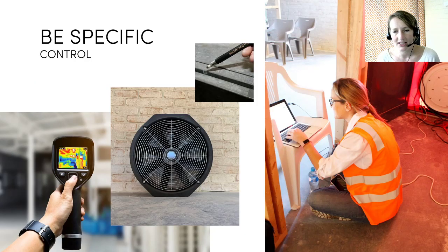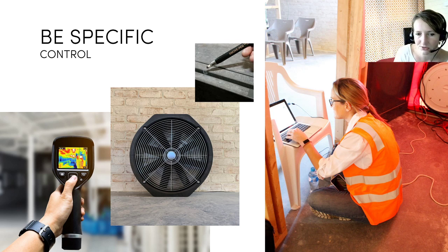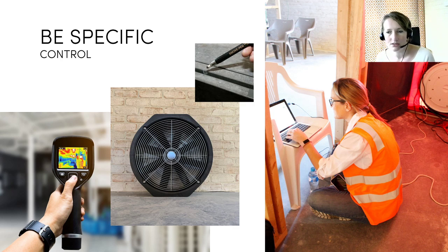And then the last thing, which is really important because it's also making everyone responsible for their work, is to actually control the building. That being said, where, for example, we work with really airtight buildings to a passive house standard, or we want to achieve airtightness good enough to put an HRV system, I think it's really important to test the building at the end of the first fix and the final result to be sure that we achieve the target we set up.